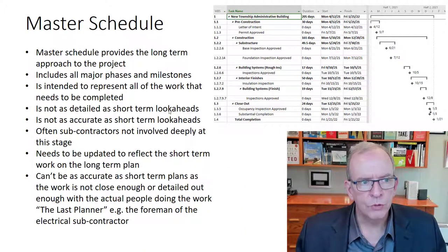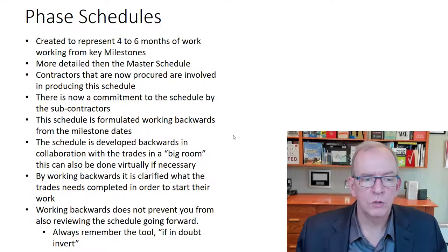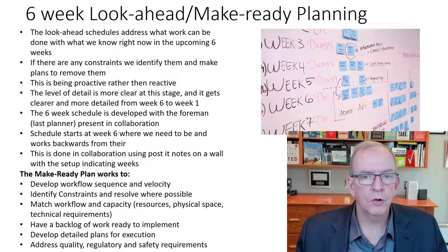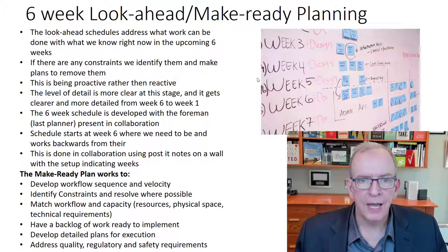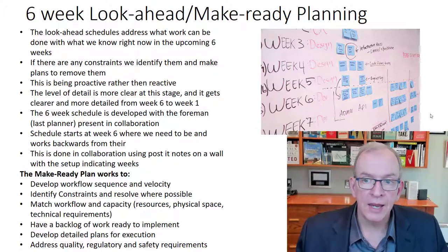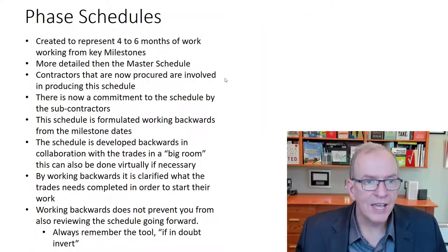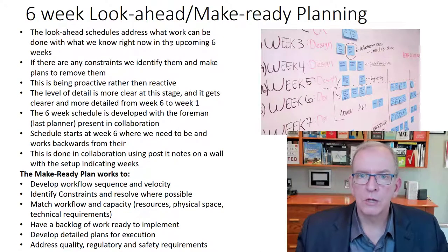And so as I kind of went through them there, I've got them in these slides here that you can just read through, but the idea is that you're working with a milestone schedule very early on, and in the phase schedules you're focusing in on a milestone. You're pulling that date from your milestone back to the current date. You're getting that make-ready planning, building that confidence that we can do this work, and developing that workflow sequencing and velocity, and getting the commitments, with each trade having a post-it note that they're putting onto your phase schedules and through your 6-week look-ahead schedules.